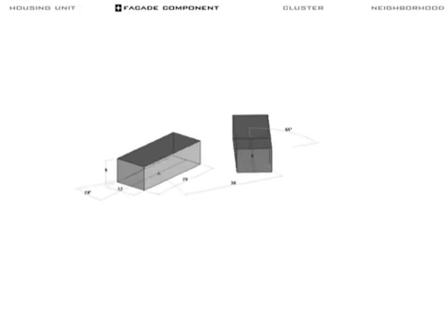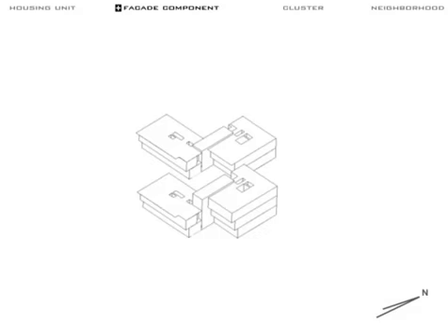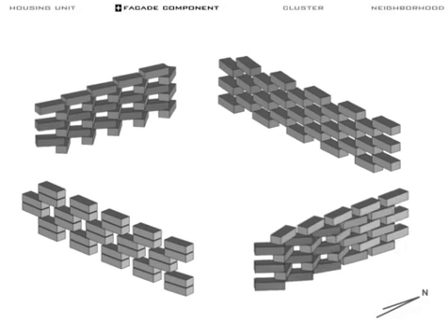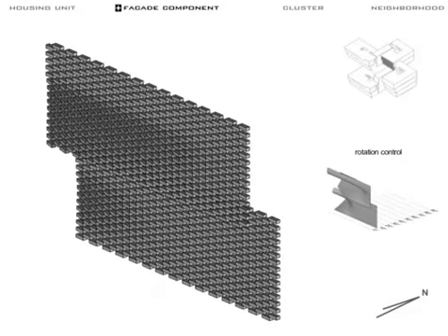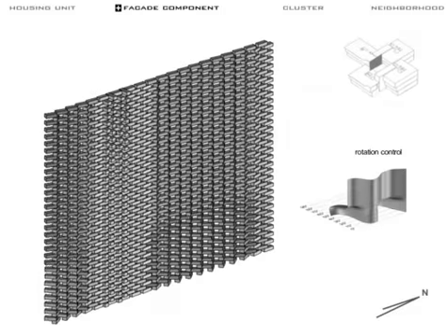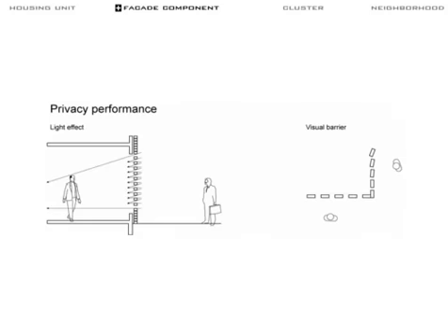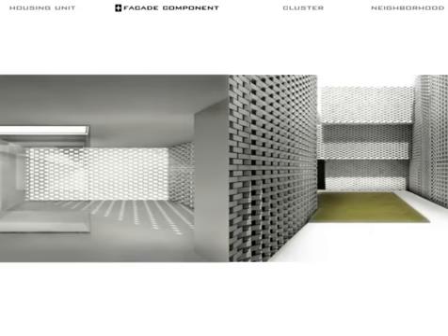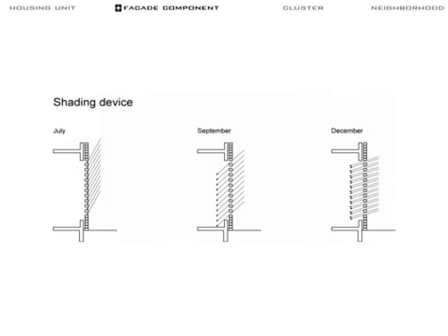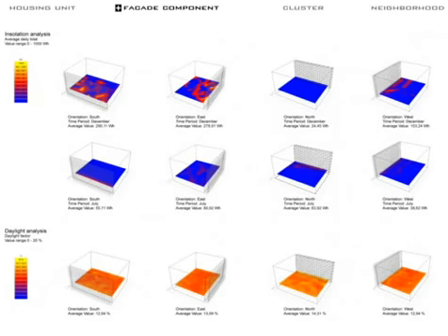Each brick, with a specific orientation, reacts to its position within the facade and on the sides of the courtyard with horizontal rotation and offset to the next brick. Therefore, the views from inside and outside can be precisely restricted while at the same time guaranteeing sun shading in summer, sunlight entrance in winter, and cross-ventilation in all seasons.